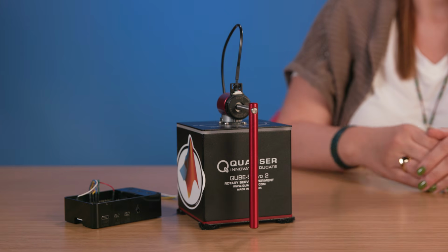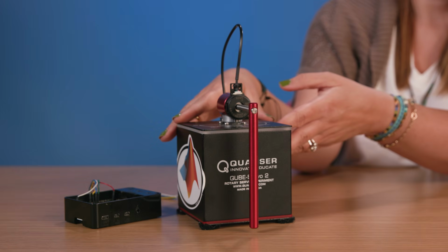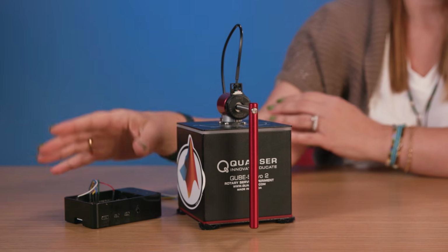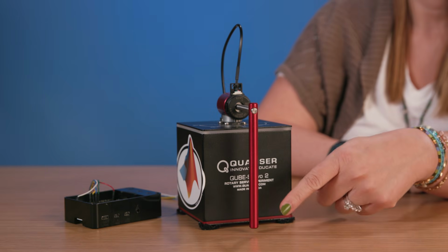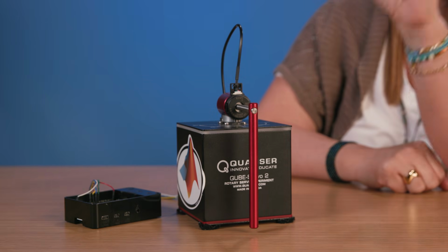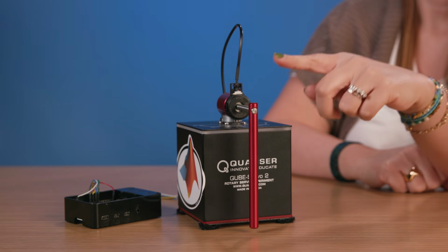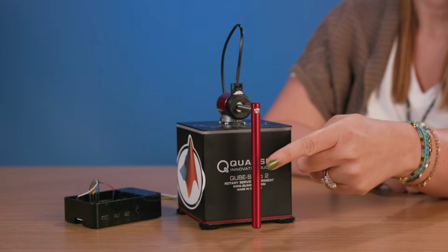Our target system is a Quanser Qube-Servo rotary inverted pendulum connected to a Raspberry Pi. The goal is to swing the pendulum up from its hanging position and balance it upright. This is a non-trivial control problem for a few reasons. The system is underactuated, meaning we can only apply torque to the arm, not the pendulum directly. It's inherently unstable at the upright position and exhibits strongly nonlinear behavior during the swing-up phase.